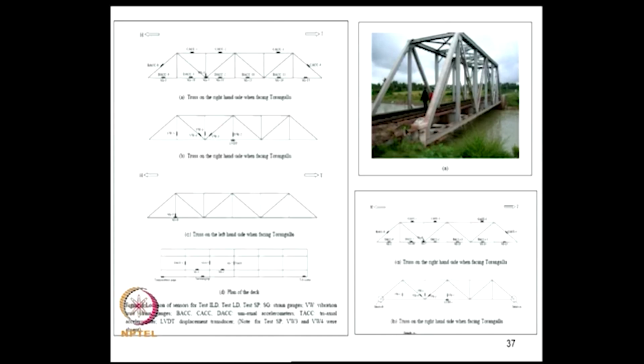So, this bridge structure was instrumented and its performance was measured under operating loads: static, dynamic, diagnostic loads where we knew what loads we were applying, and ambient loads which were due to the prevailing traffic on this bridge line, and so on. Now, the question is, after obtaining this data from this existing bridge, suppose I were to make the finite element model for this and conduct these tests numerically on my finite element model, I will still be able to predict what should be the readings from these sensors, but those predictions will not match with what exactly we have observed in the field.